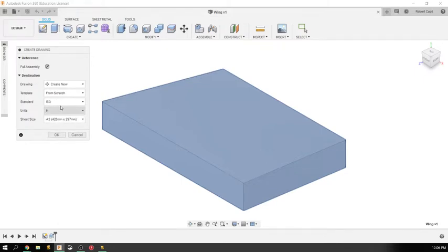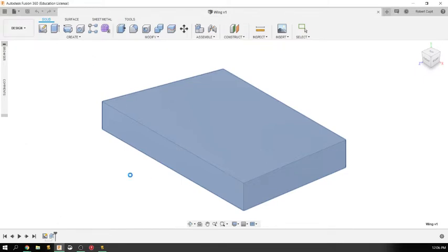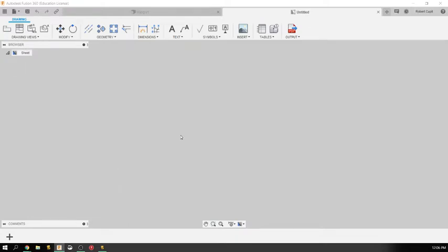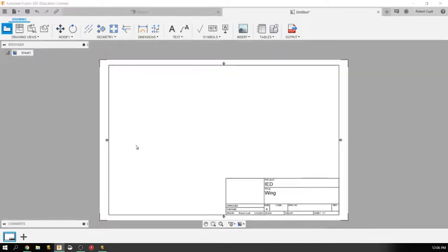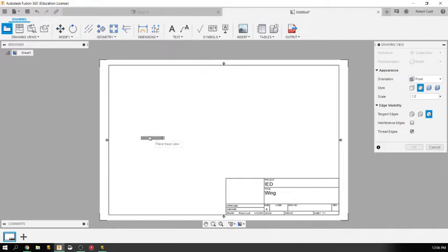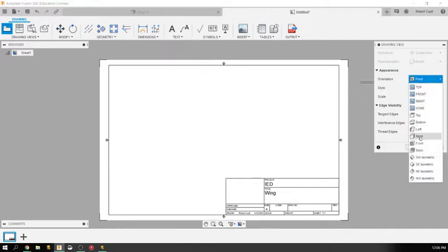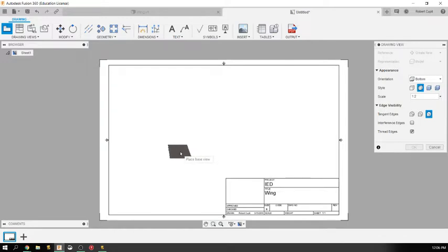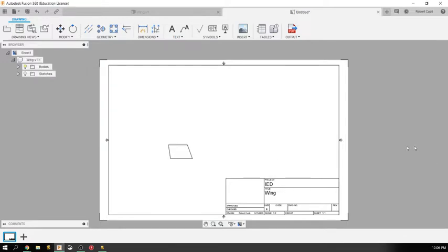Let's select ASME. After I bring this in, just a quick review on how to do this again. By default, it'll bring this open. You come over here, you pick your orientation, and you're going to make a multi-view. You have the one corner, you hit the second button way up here, and you're going to see the projection. You click once, you drag it up, that's the top view. You drag it over, that's your side view. After you're done with that, you can go into the isometric view, right-click, press OK.